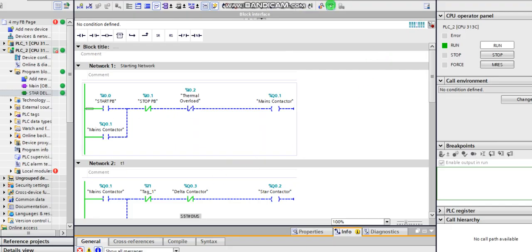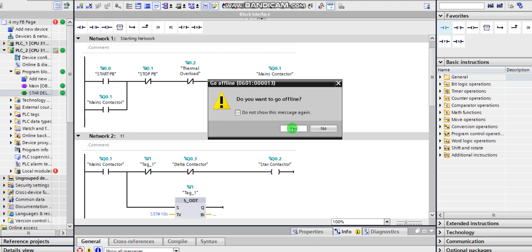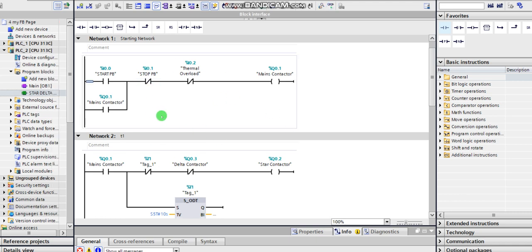This particular one now, the termination of this to PLC is what I just showed you in the other control software. How you can do this? Okay, let me identify how many inputs we have here. We have a start button, we have a stop button, we have an overload. That's 3 input bits only that I need.